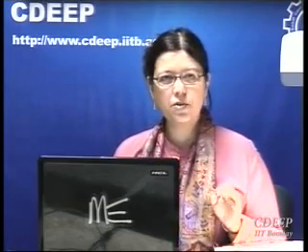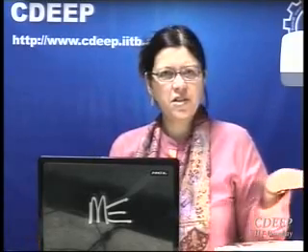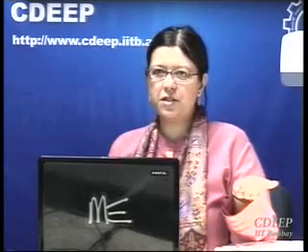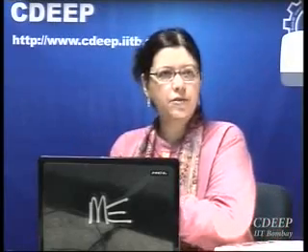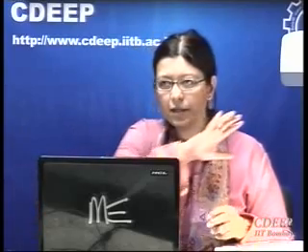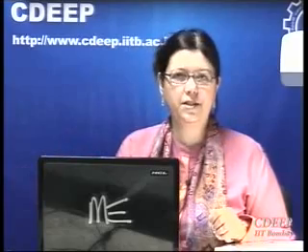So what would be the sampling rate at the input of the first stage compared to the sampling rate at other stages for a pipeline ADC? They are the same, exactly. You are sampling at stage 1 with the same rate as at stages 2, 3 and 4. Therefore, your sampling rate is uniform across all stages.